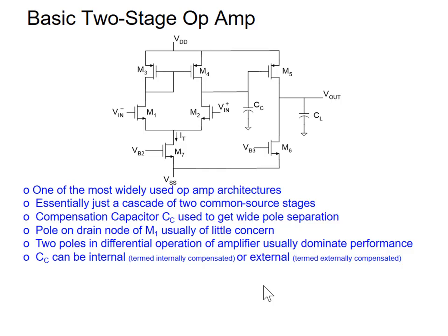It's a diffusion capacitance here, a diffusion capacitance here, and two gate source capacitances in parallel. But the impedances are an output conductance here and a gm here. So we've got a fairly small resistor and a fairly small capacitor, which means that it's a real high frequency pole. So we can usually neglect that pole on that node.